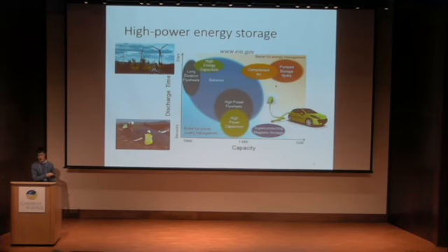So it may be good for long-term energy storage, but may not be efficient if the energy generation has some rapid fluctuations. For instance, nowadays we want to use more energy from renewable resources, such as wind and solar power. These energies may fluctuate when conditions change, like the wind or sunlight. So in addition to the high capacity storage method, it's better to have high power energy storage that can charge rapidly enough to improve the efficiency.